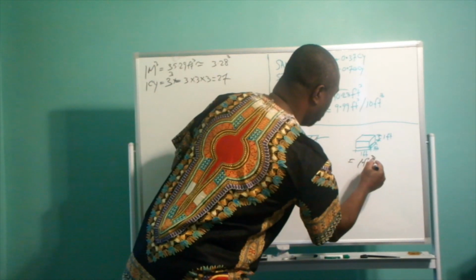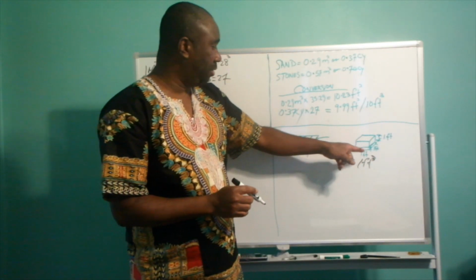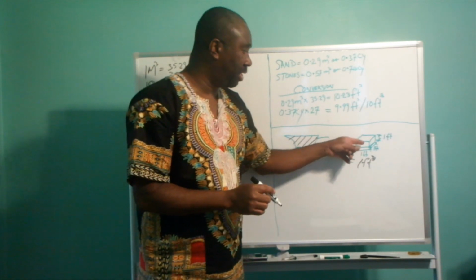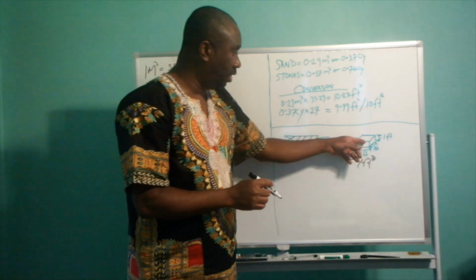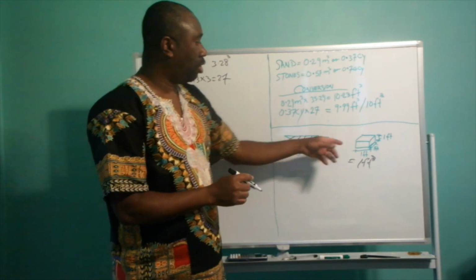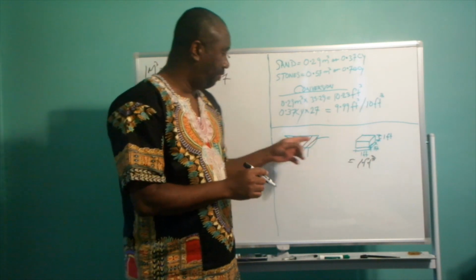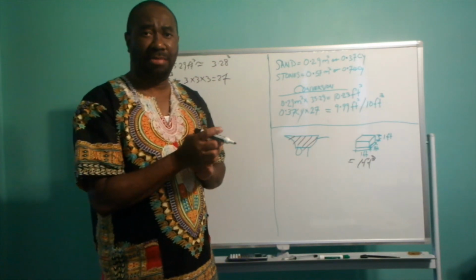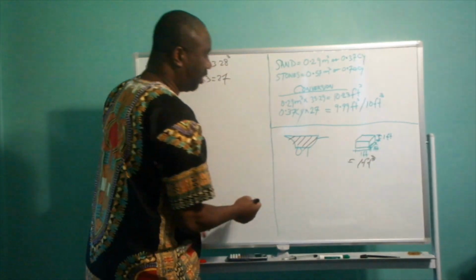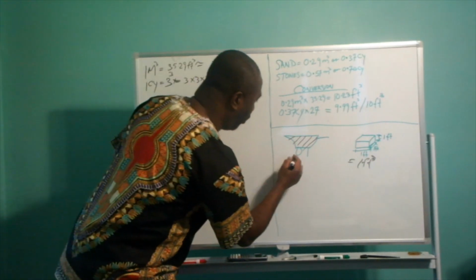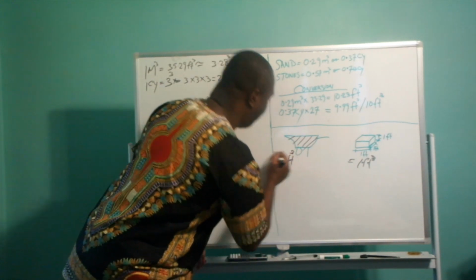So what you will do is fill this measuring box with sand, and use it to fill the barrel, and you count how many times this measuring box will be needed to fill that barrel. So let's say, for argument's sake, it takes 10 of these measuring boxes to fill this barrel. Then you would know that this barrel measures 10 cubic feet.